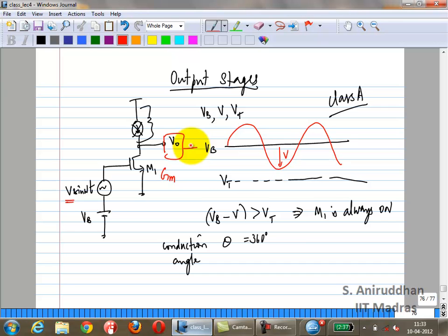Absolutely, that's right. So what the capital GM you are calculating is what is called the effective GM. You can define it, say that this transistor has this large signal transconductance, but it is a function of VI obviously. And you are right, at every point it will have a different value, and that is why we are calculating the overall effective transconductance. This is useful in specific cases. This kind of using large signal GM may not be useful for calculating the gain of the stage, for example.